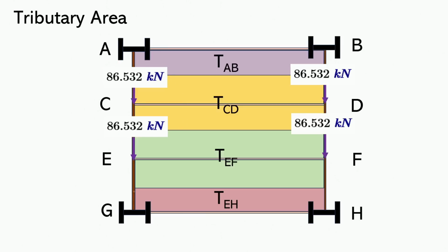And then, we also have reactions here. Now, this is equal to 44.856 kN according to what we have solved earlier. So, this is also 44.856 kN. And so, if we will consider girder AG, then we will include the weight of the girder AG plus these concentrated loads, this and this. And then, they will act at their corresponding points. And so, this is it.